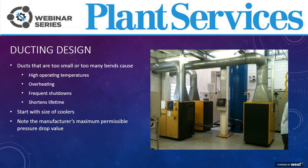Maximum permissible pressure drop is key. Compressors generally have an internal cooling fan that pulls cooling air into the package and then forces it out again. This fan is, in effect, both pulling and pushing air. When you connect ducting to either side of this fan, it creates a pressure loss. This applies to the area upstream of the fan, which is inlet ducting, and downstream of the fan, which would be exhaust ducting. For a given flow rate, the smaller the cross-section of the duct, the larger the pressure loss.